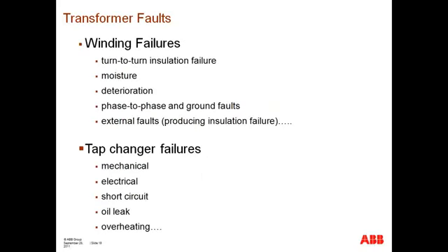Now, what are some of the common failures that are recognized? So transformer faults. Well, several of them. You could have turn-to-turn insulation failures, and again, I'll refer you back to the slide where you have the cross-sectional cut of the different windings, where you could very easily see that if a breakdown of insulation occurs between those two turns, then a short circuit could occur between the two turns. Okay, and we'll talk a little bit later as to why that is a hazardous condition.